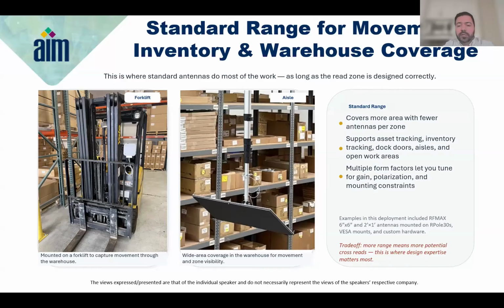The trade-off with this, right, is that more reads means more potential cross reads. That extended range means that you're going to pick up more tags, but it's not always something that you're intending to pick up. So we really need experts in place to define, hey, this is what we're looking for, and also to take into account what's going on in the environment around us. If you look at all this warehouse racking, I'm sure as most of you know, there are a couple of things that RFID just doesn't really get along with.